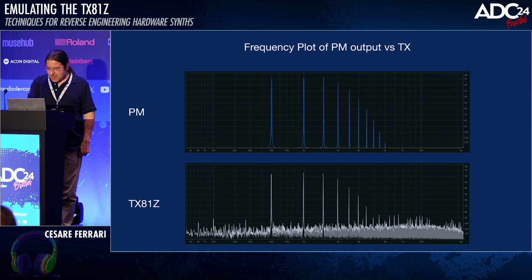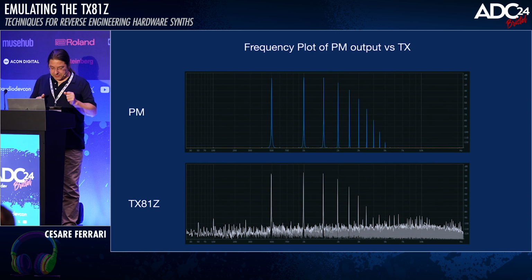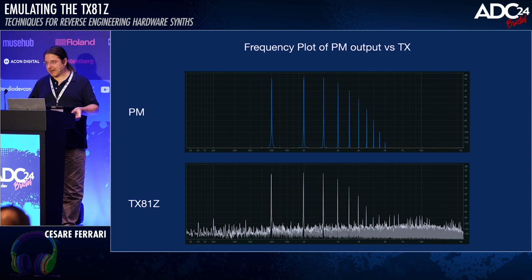Let's highlight a few things. There's a noise floor, fairly obvious. There's mains hum, 50 hertz and 100 hertz. There's some other cruft, I don't know what these are, some funny spiky bits. There's clearly other stuff going on. Now, as I said before, the TX81Z is a totally digital domain instrument, but it uses a DAC.